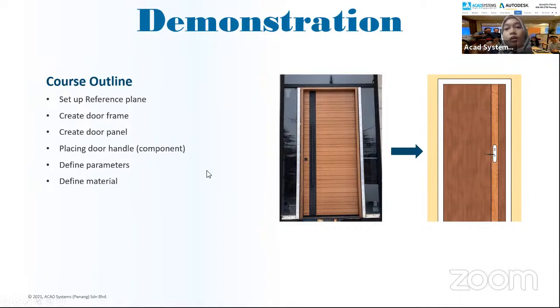For the course outline, to create a door family, firstly we need to set up the reference plane. Please note that to create a door family, we will be using the reference plane constantly, because the reference plane plays an important role in creating the families and the parameters.